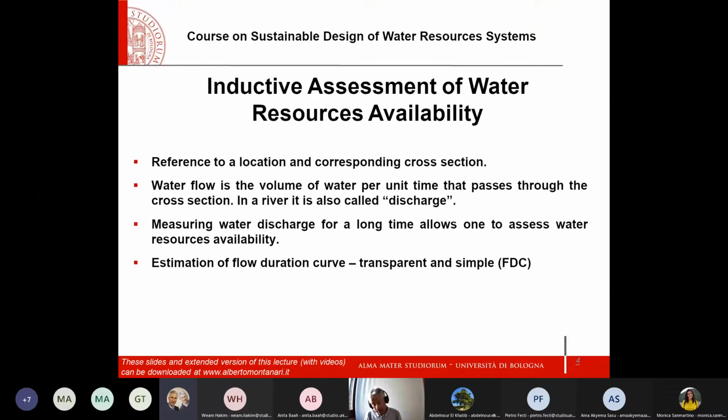It's delivering a lot of water because of its high velocity. The water is frequently replenished, and there is a rapid exchange time. What does it mean? It means that if water flows quickly, the quality is higher with respect to water in lakes, where the residence time is much, much higher. And therefore, it was a classical solution to settle down, to build cities close to rivers and take water directly from the river. At the beginning, it was also very easy because the river was not polluted. And then some problems came with water quality, but it was a later problem.